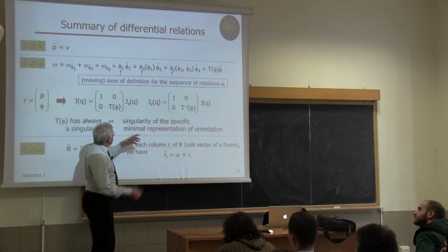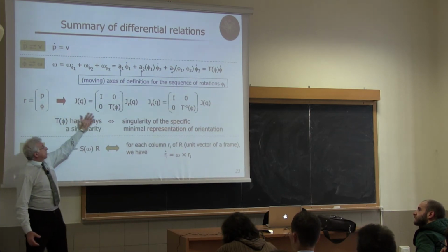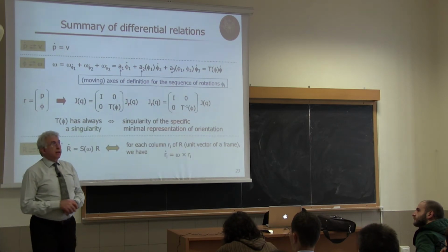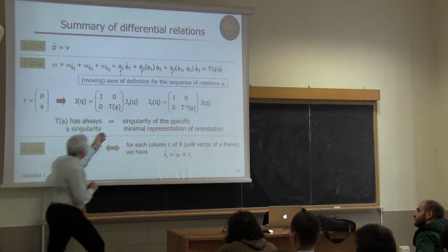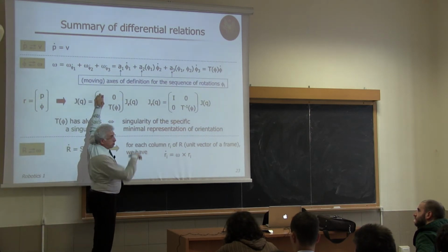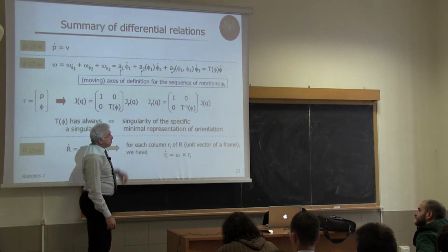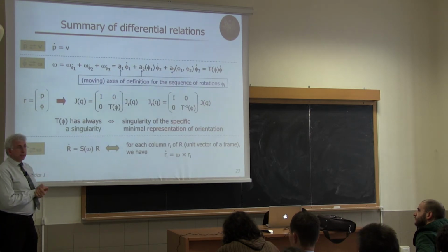So if I generate the geometric Jacobian and the analytic Jacobian, the relationship between the two is as stated on the slide. There's an identity here because the linear part is exactly the same, while this matrix appears in the angular relation between the 2 matrices.